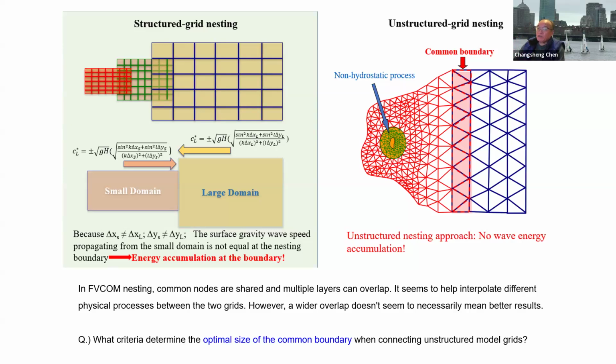However, if you have a river plume, for example, a coastal river plume coming out, the water can reach the boundary for a certain time. So if you do one-way nesting, your boundary condition changes, right? Not only tide, there is also fresh water coming from inside to outside.